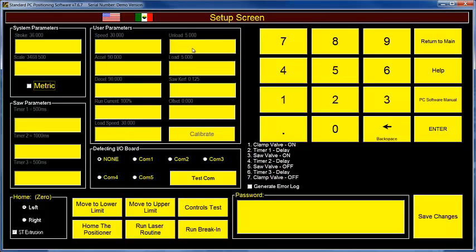The unload has to do with when you're in absolute mode. There's a button on the screen that says unload, and when you press that button, the razor gauge backs up so you can maybe get a short part out from near the saw and then move back to cut another part. This is the distance that it backs up when you press the unload button.